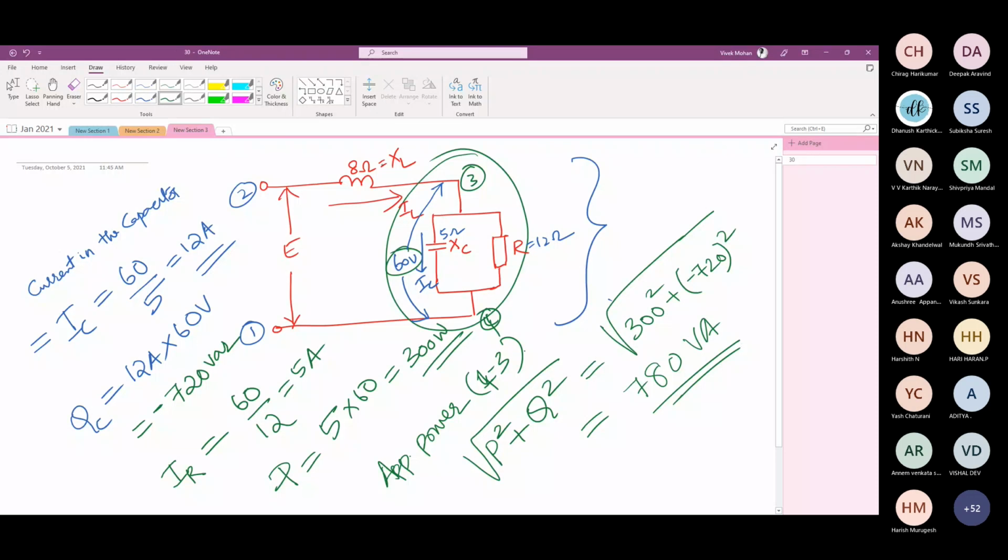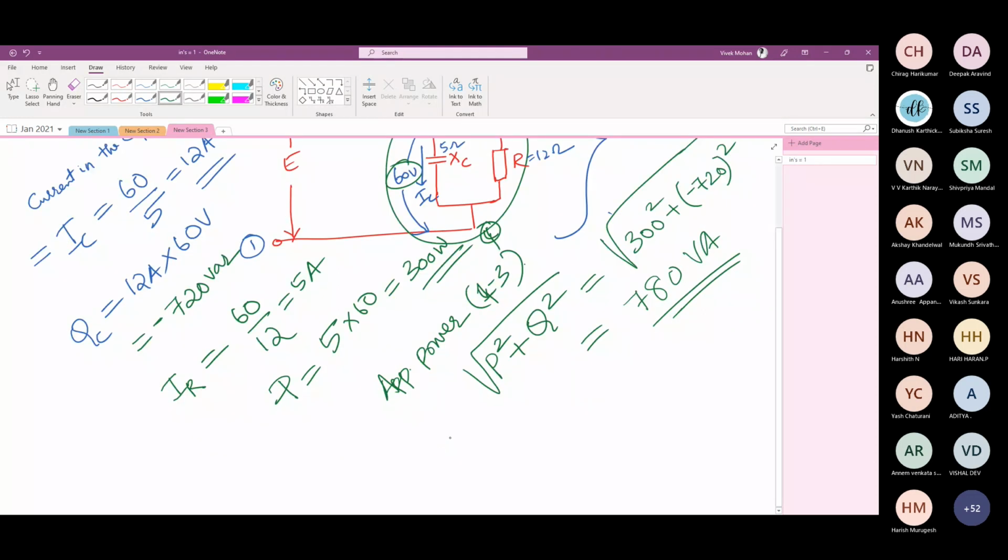Now I am going to current IL and this one, reactance. What is my current IL? How will I find my IL? My IL equals S divided by, suppose I am taking, if I am using S, then what should be in the denominator? ZE. Now what is this value? What is the value in the denominator then? If I am taking S.